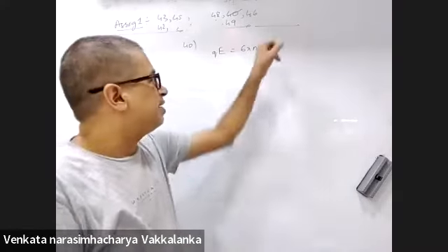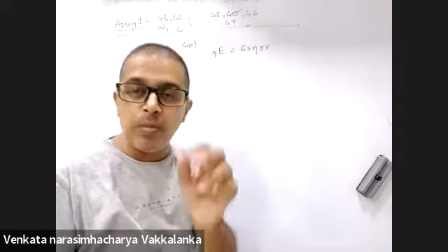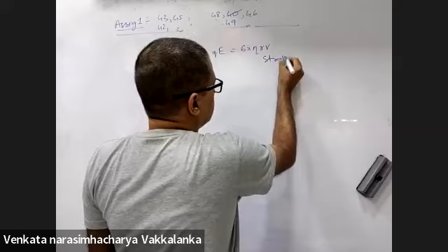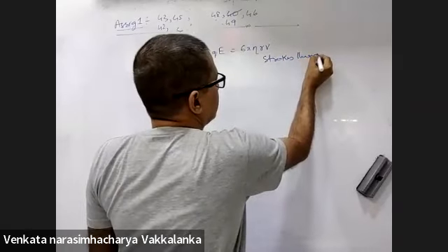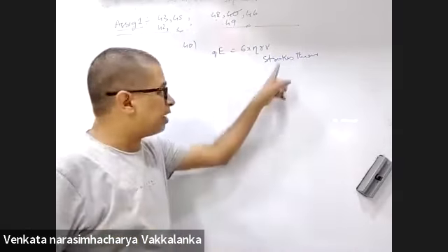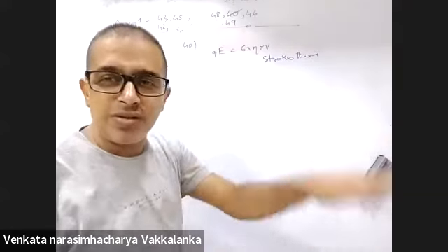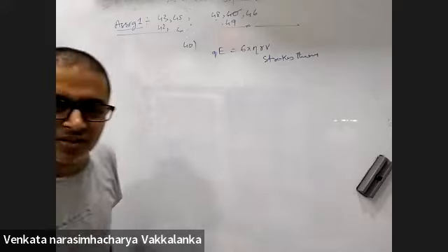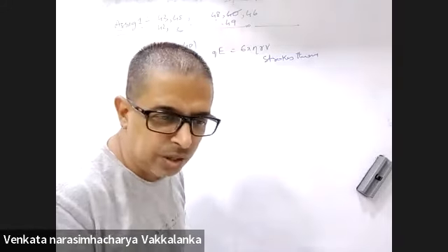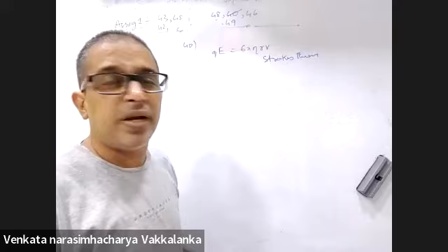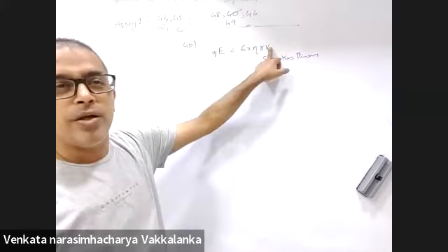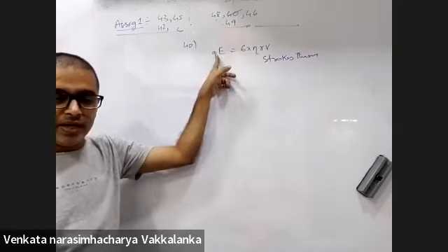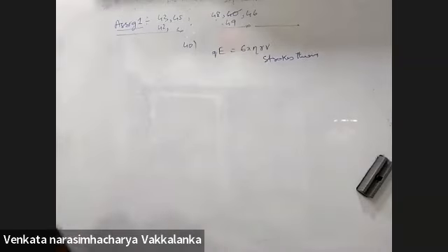Fine. Anyway, this is the force on a spherical body due to viscous drag force. This is called Stokes theorem. Temporarily, besides that question, make a note of it and keep it. Once that is done in fluids, you equate these both forces because he says it is moving with uniform horizontal speed, velocity is also given. So these both forces should be equal. You will get Q, from Q you will get the value of K.